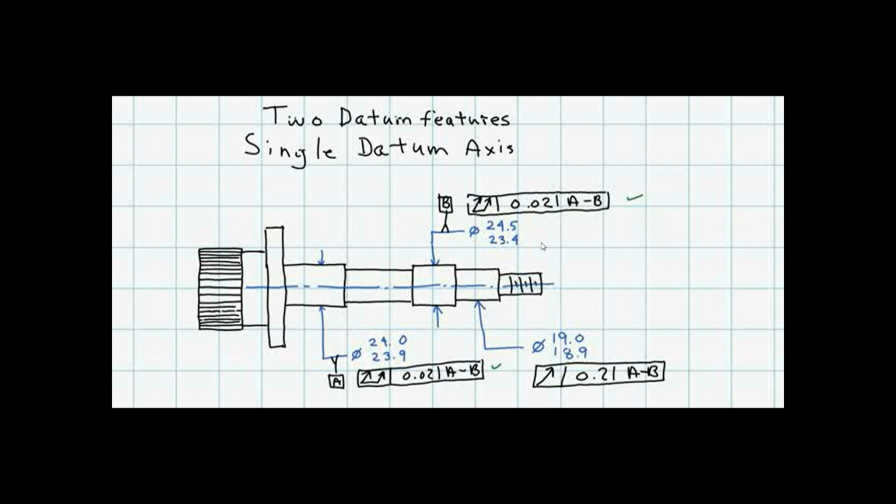So what I want to do is illustrate what those datum simulators might look like two-dimensionally. So we would have a cylinder of some flavor that collapses onto datum A until we get the maximum number of points of contact, while simultaneously our datum B simulator is a cylinder that collapses as well until the maximum number of contact elements with the extremities of that as-built feature is established.